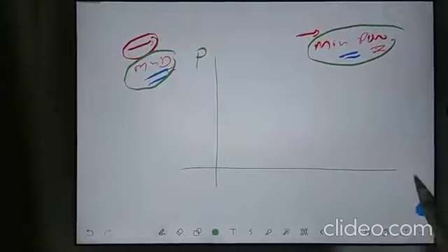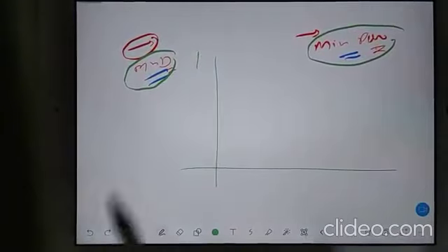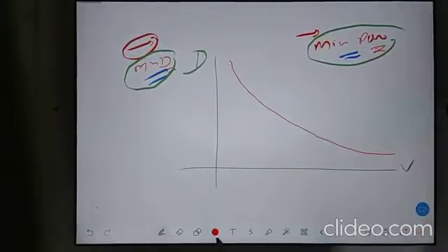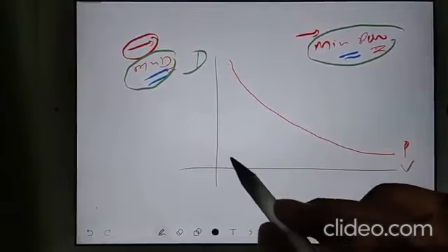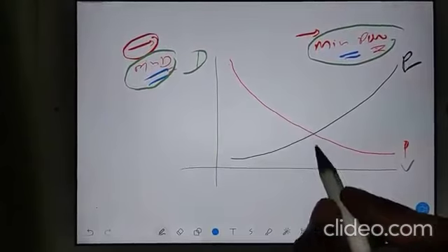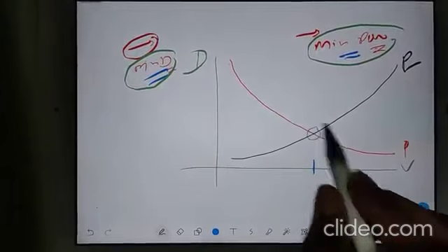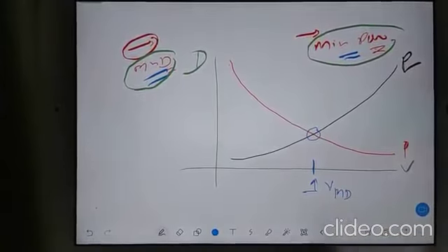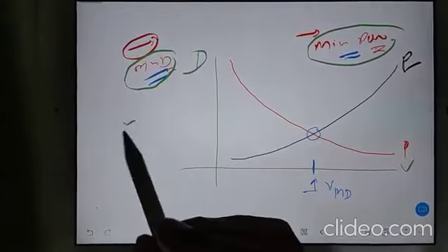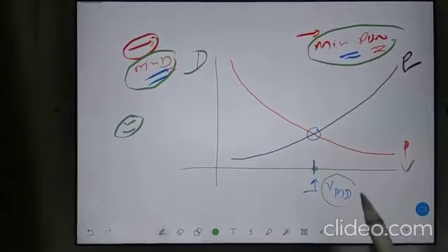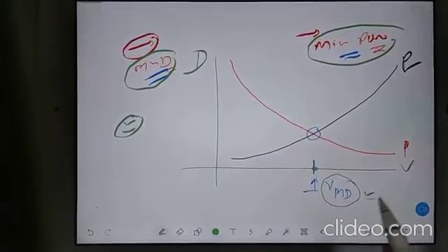Here you have the drag versus velocity graph. Sorry, this is drag. So this is your induced drag and this is your profile drag or parasite drag, you can say. This is the velocity when both drags are equal. This velocity has a special name: minimum drag velocity. I mean, the pilot is flying the aircraft at such a velocity that the aeroplane is experiencing minimum drag.